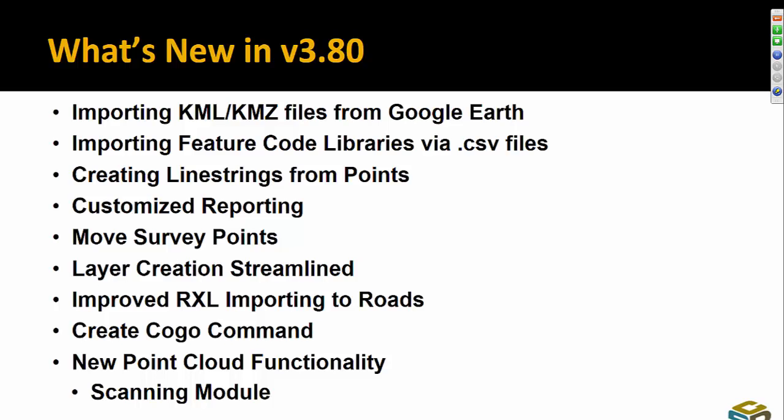Pretty simple. Creating layers, that one will be a super quick little demo that just gives you the ability, whenever you're creating an element, whether it's a point, a surface, a line string, a corridor, contours, whatever object you're creating inside of TBC, you're now able to simply hit the space bar, and it takes you into the layer manager to create a new layer. So it makes the creating of layers a little bit more streamlined and much more effective.